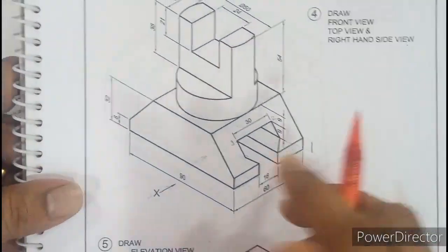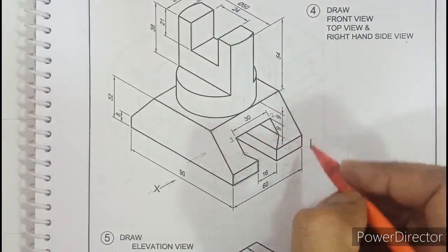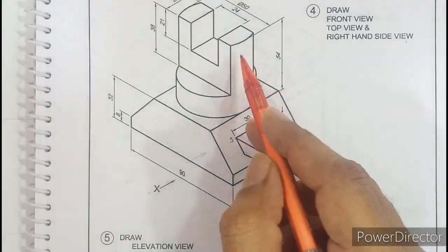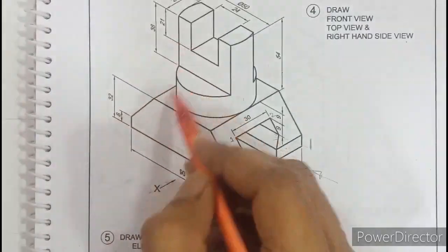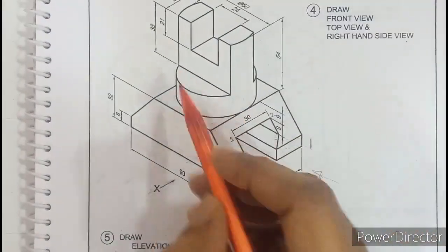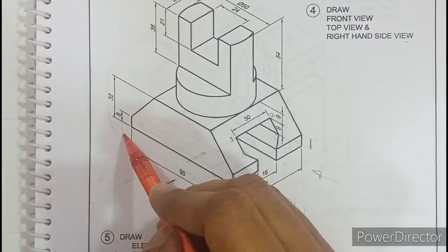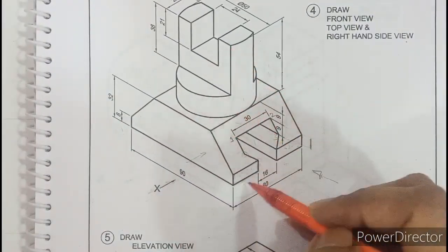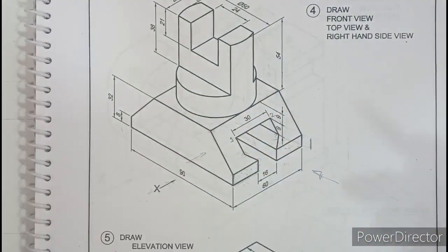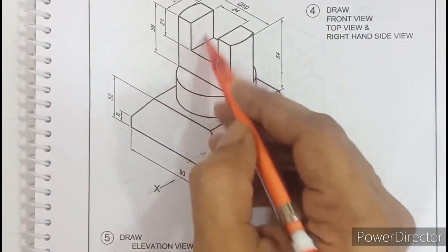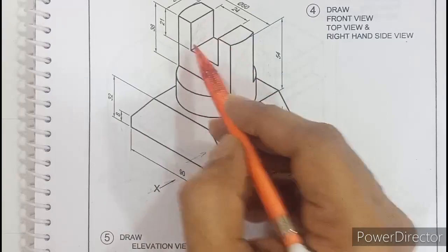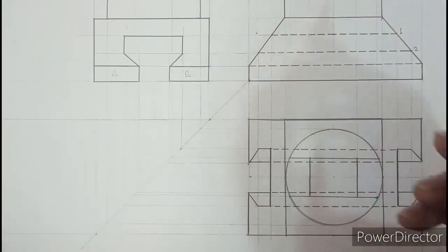And if you carefully observe the diagram, when you look in the side view, the front half of this diagram is symmetrical with the rear half. So what is happening is there are no hidden lines, because all the edges in the rear side overlap with the front edges. So there is nothing like hidden line to be drawn here except this surface what we did before. So except this cutout or slot, there are no hidden lines in the side view. So that is how we have completed this part.